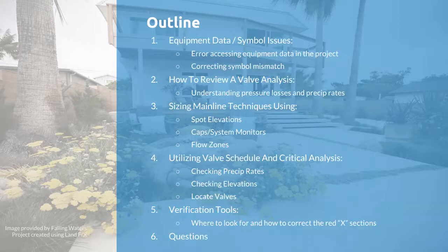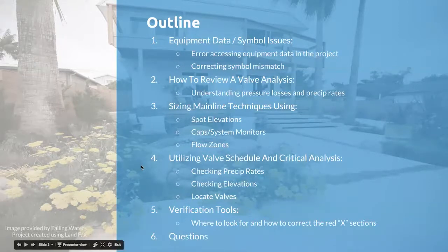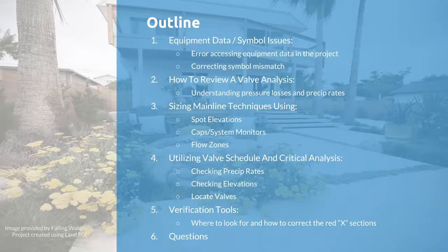And then obviously utilizing those schedules, the valve schedule, critical analysis, to really check and make sure that your precip rates and the data that you've actually put into the design is what it is, and how to maybe use a couple other little hidden tools that you may not know about. Locate valves is a great one if you're not aware of that one, so I'll try to show that one as well.